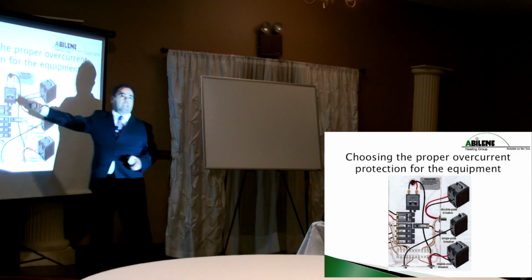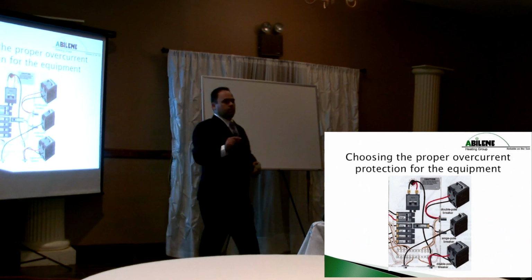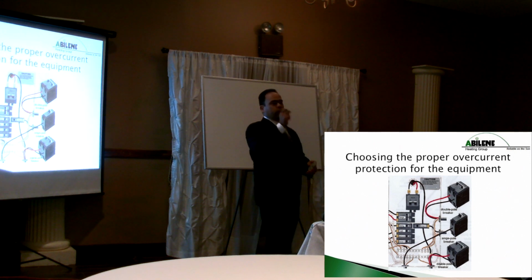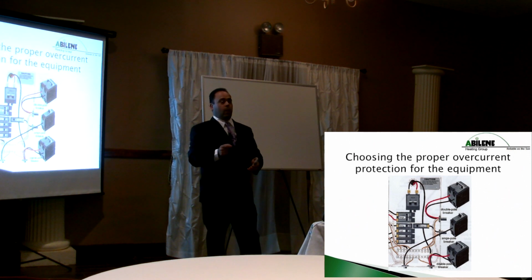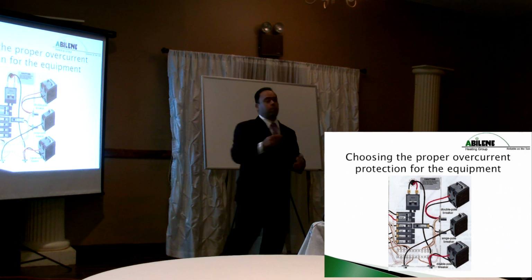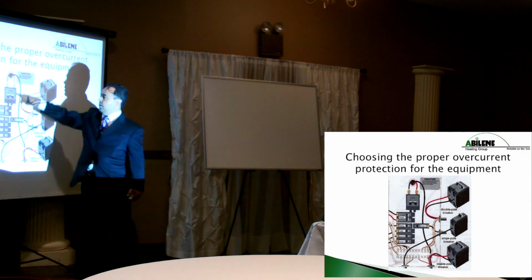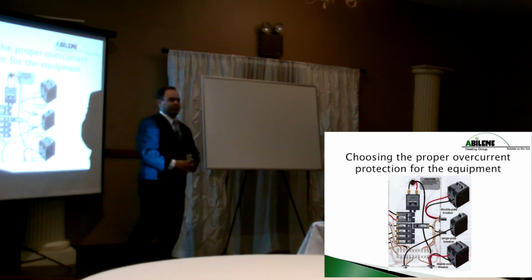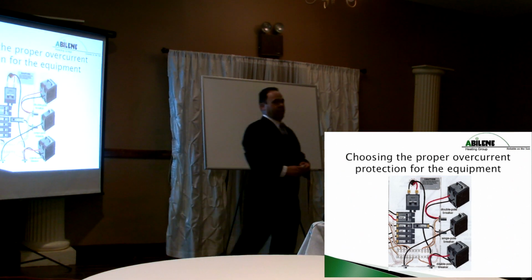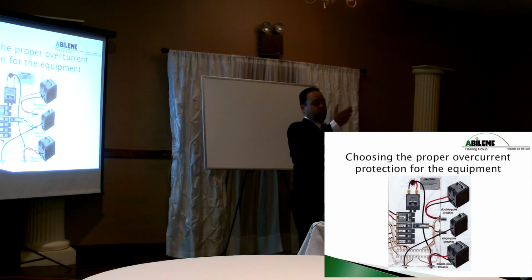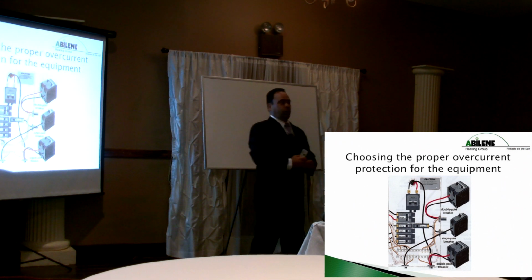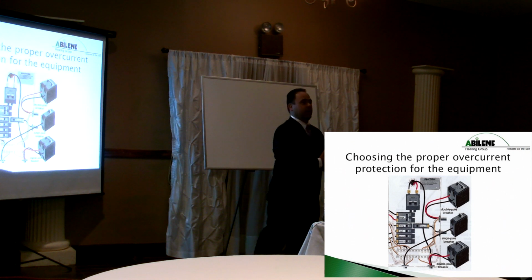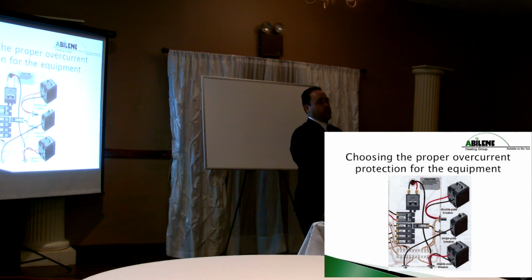The breakers are rated at an inrush current value. And you'll see them. It could be 10,000, it could be 20,000, it could be 30,000. When you purchase that breaker, you have to make sure that you coordinate them properly, that this one is a lower range than that. You understand? It's called fuse coordination. You'll see it on the fuses as well. And it's in the code now, too. It started in 2010, where you have to prove fuse coordination.